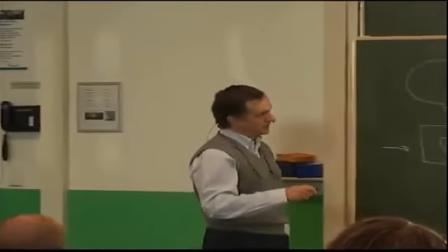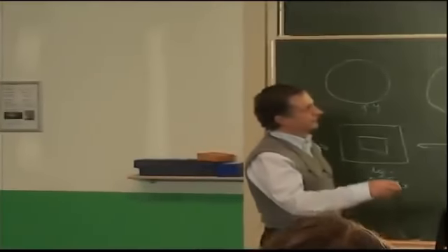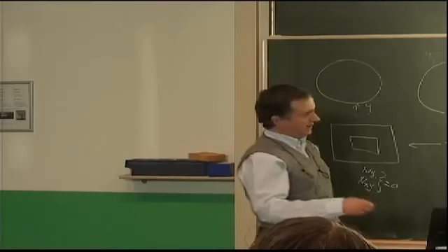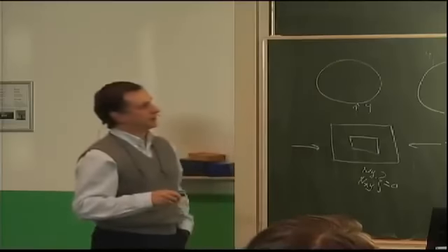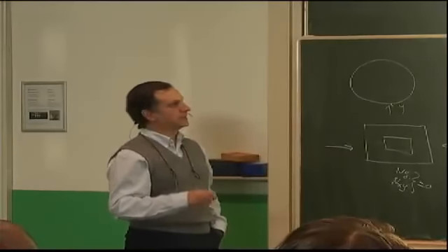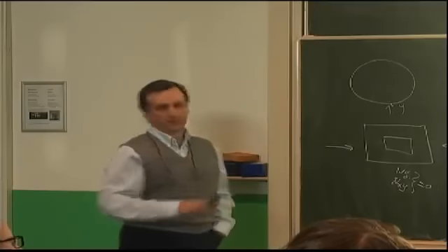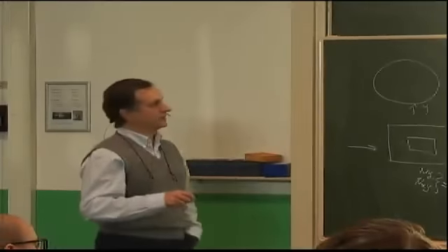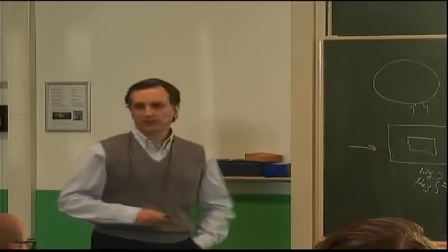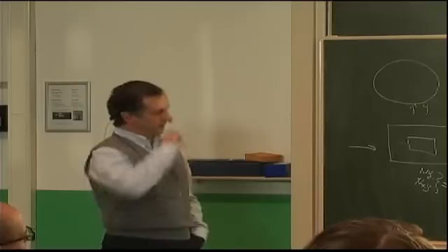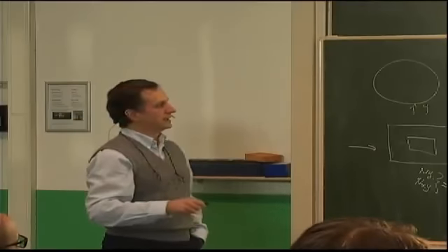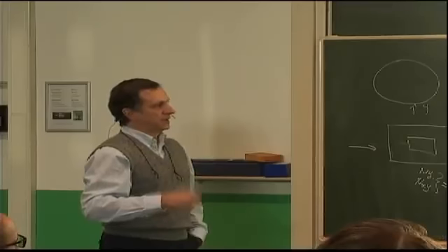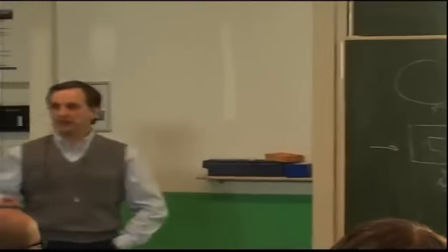So I substitute this in my governing equation here. And I factor out the sine m pi x over a and sine n pi y over b. So if I factor that out and I cancel it from both sides, I will get this mess on the left-hand side equal to this mess on the right-hand side. Basically, that involves the AMN on both sides, and that's not very encouraging because AMN would cancel. And it involves the AR, the aspect ratio. A over B is the length along which load is applied, B is the width, and we call it AR, aspect ratio. Now, one solution says AMN equals 0,